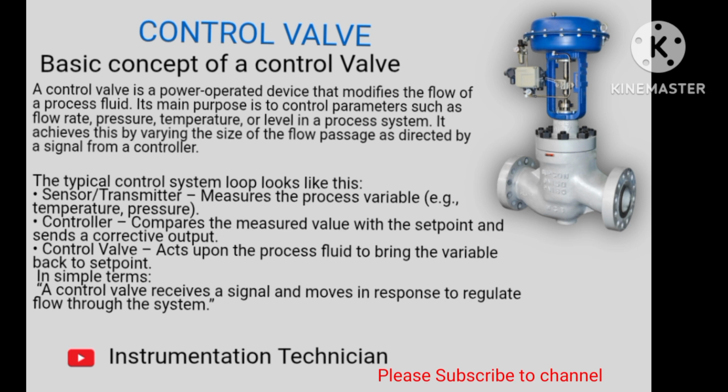Basic concept of a control valve. A control valve is a power-operated device that modifies the flow of a process fluid. Its main purpose is to control parameters such as flow rate, pressure, temperature, or level in a process system. It achieves this by varying the size of the flow passage as directed by a signal from a controller.